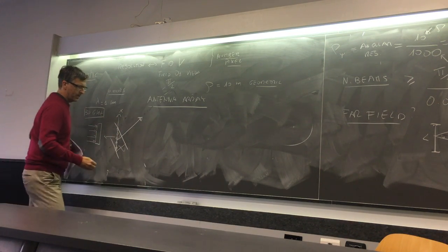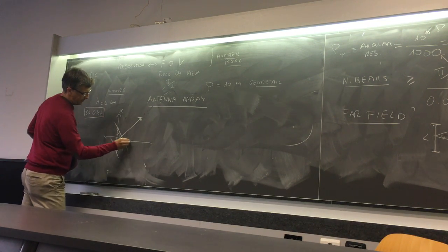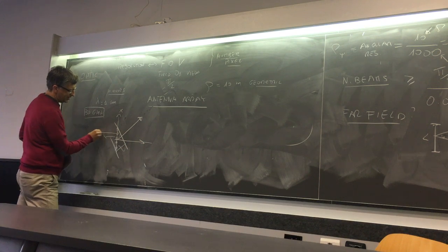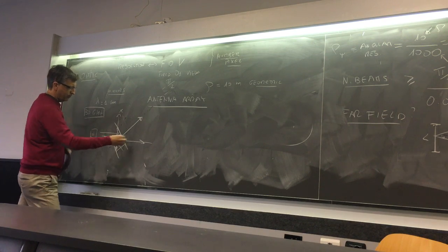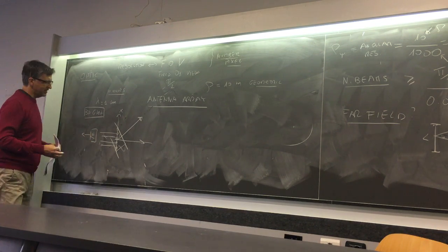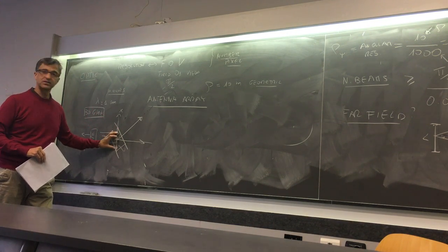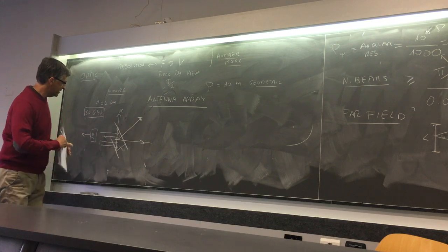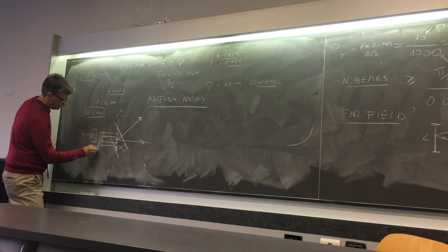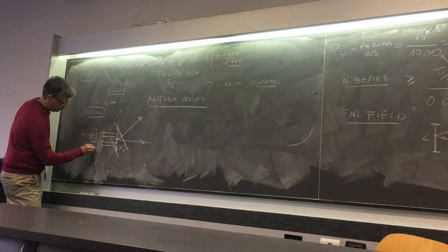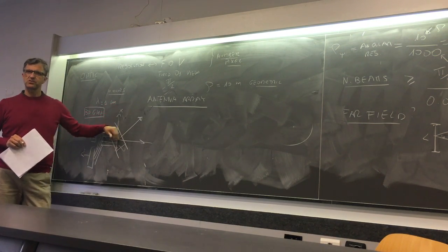So, for example, if I wanted to look at the gain in this direction, I take all these numbers and I sum them together. If you take all these numbers and sum them together, you just use the antenna in a classical way, as if it is a fixed antenna. But if you have to rotate, you take these numbers and you put different coefficients. So you take the same set of numbers and you put a second set of coefficients, and then you steer the beam in this direction.